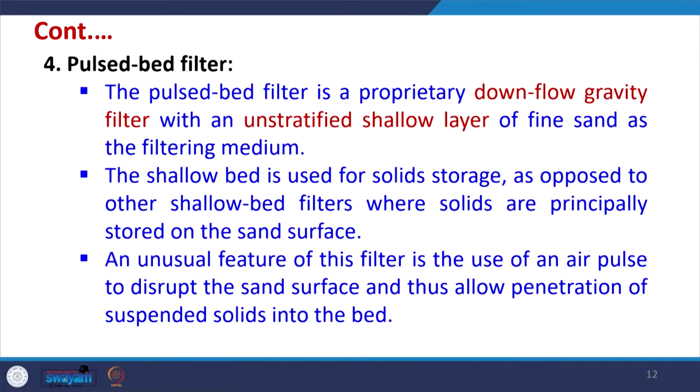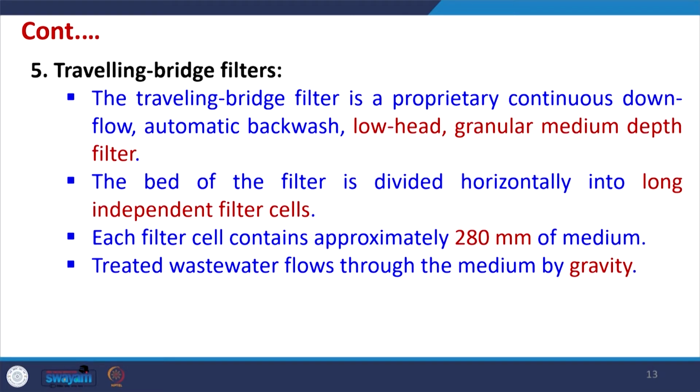An unusual feature of this filter is the use of an air pulse to disrupt the sand surface and thus allow the penetration of suspended solids into the bed. So, the air pulse is used for disruption after some time, so that the solids can go into the bed where they get accumulated.